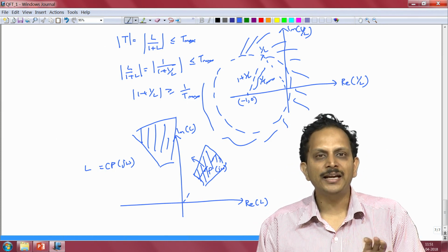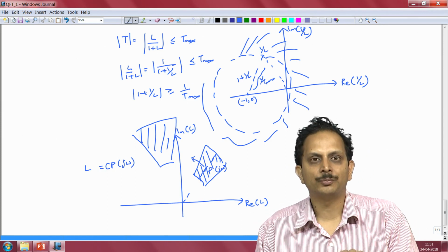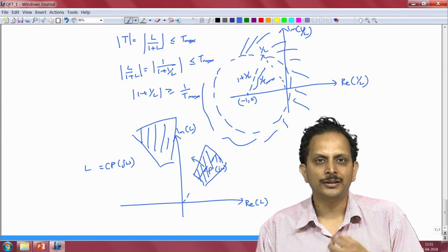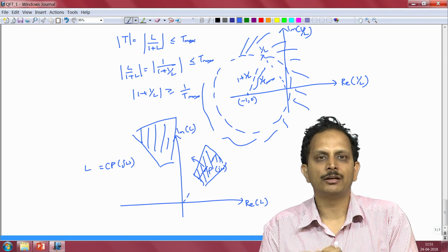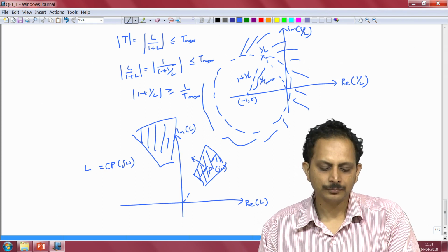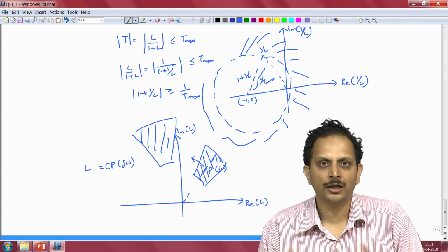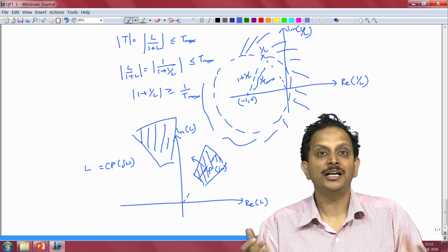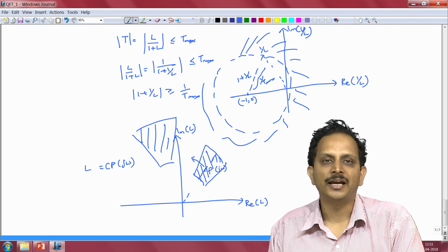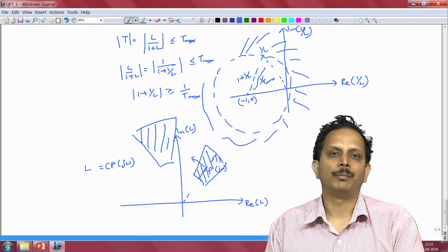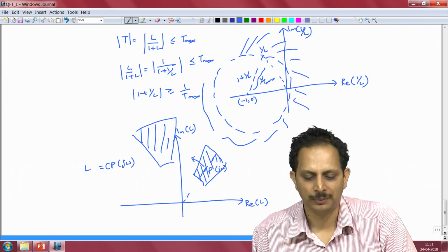And this variation in size that occurs because of our controller transfer function is what makes the Nyquist plot an unattractive plot when we are dealing with uncertain plants, because we have not yet designed the controller and we do not know exactly by what amount it would amplify or rotate the area that is occupied by P of j omega in the complex plane.